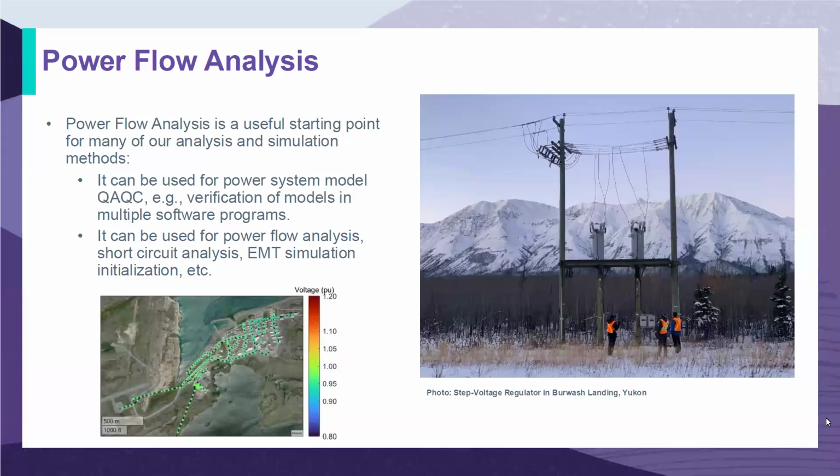But one of the challenges that we face with a lot of power system analysis is that it assumes a balanced system, which you cannot assume in an isolated grid. Even with, say, for example, low inertia systems, how that impacts everything is something that not all power system models use. So we started off with MATLAB Simulink and developed models where, say, for example, the Woodward governor model. We use DGOV1 as our base model. You implement that with Woodward parameters to the best of our abilities. So we use standard power system models supplemented with real world data to the best of our abilities and assumptions, and then update them as need be to meet our needs. So we started with MATLAB Simulink, but is that the best tool? No. You'll never find a best tool, but we have trade-offs.